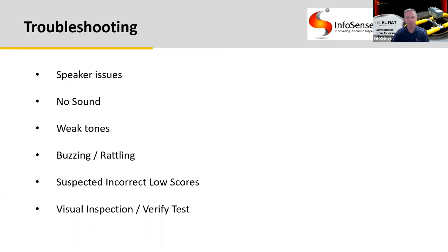If you're having speaker issues, the unit will once again need to come in for service. The speaker is calibrated to the device, and that can only be done in our shop. The speaker is expected to last roughly 3 years, but is essentially the only moving part that will eventually wear out. If the speaker sounds bad, or you think you are getting incorrect scoring, first look at the speaker and see if there is any debris that can be removed. If the speaker looks fine visually, then try running the verify operation test. If you get a 7 or below, there is an issue that needs to be addressed by our repair team.